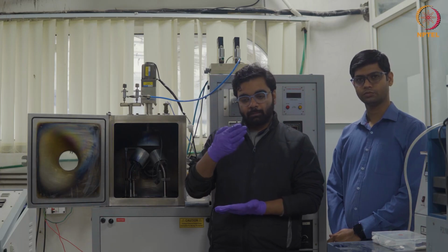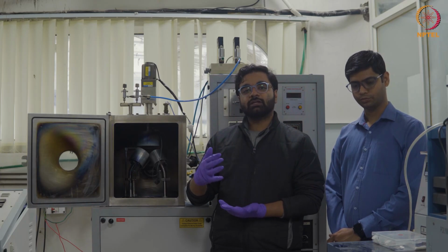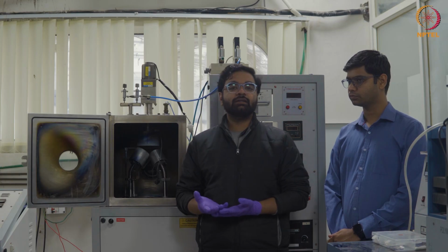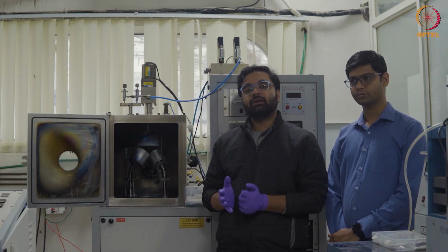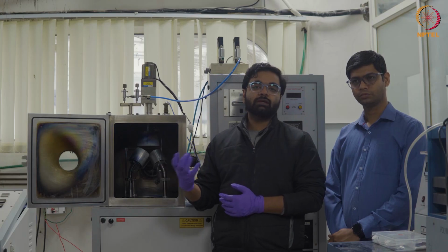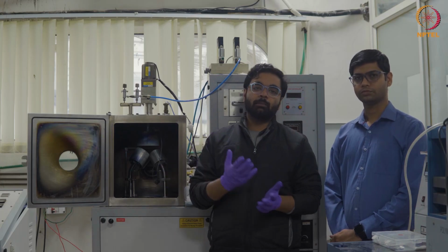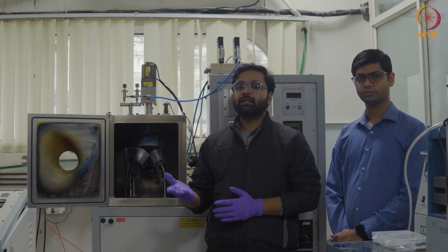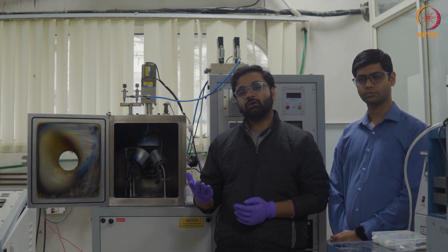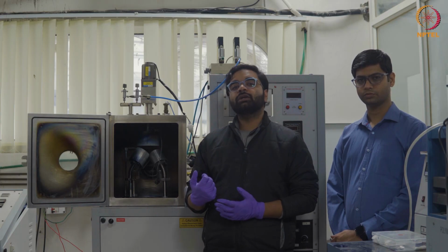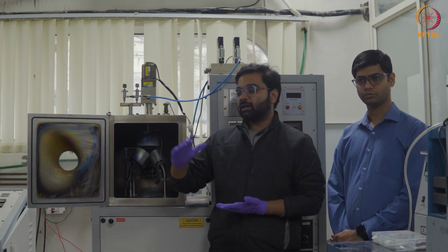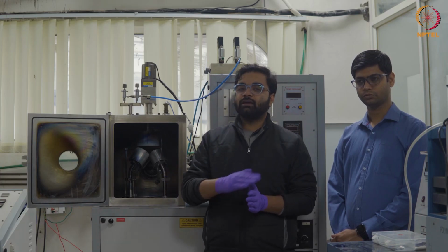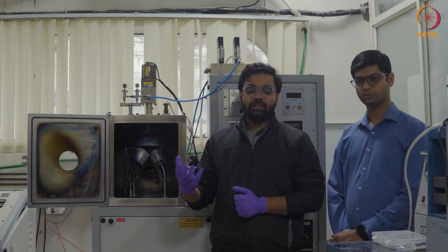So what is it used for? It is used for printing different kinds of sensors and different kinds of materials. As far as our experimental understanding is concerned, there are a lot of materials that we have explored. We have explored pure materials such as aluminium. Then we have explored alloys such as shape memory alloy, like nickel titanium. Then we have moved towards exploring ceramics such as zinc oxide, and now we are exploring the feasibility of printing silicon carbide. So that is the range of materials: low density and high density materials. Various ranges of material have been tried and successfully printed.